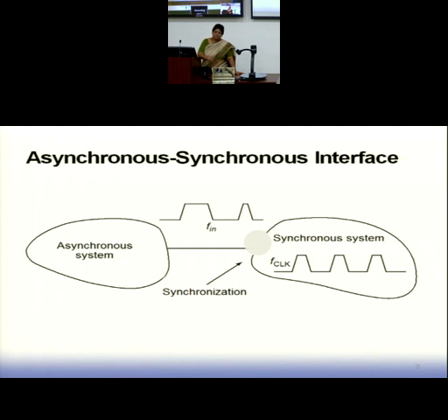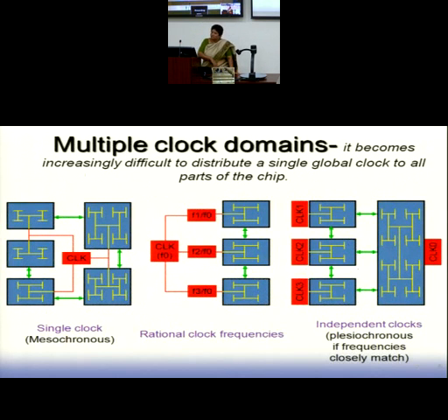Now I have given you an example of a keyboard, but it can happen in a different fashion also. You may know that in a system I may have multiple clock domains. Nobody says that all the blocks should operate at the same frequency. To save power, if a certain block is computing early, what is actually done is that we make it operate at a lower frequency, so that by the time the latest output comes, this output would also be ready. It need not compute so early and then remain idle. So we can have multiple clock domains in our circuit.